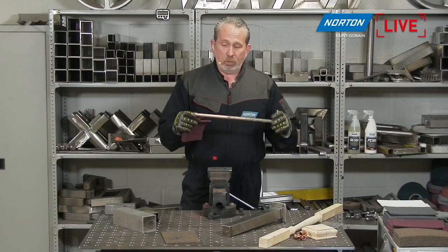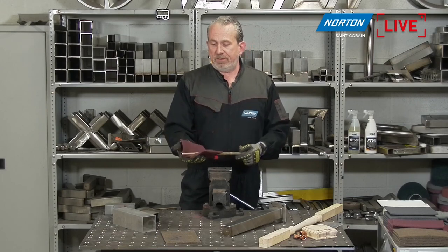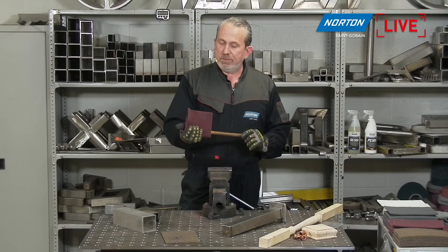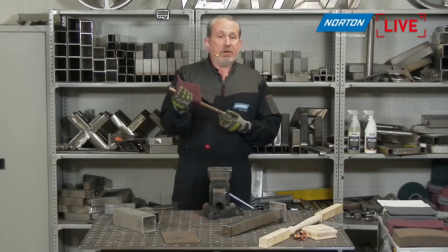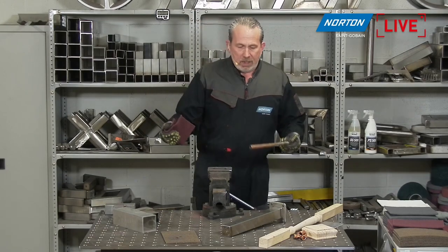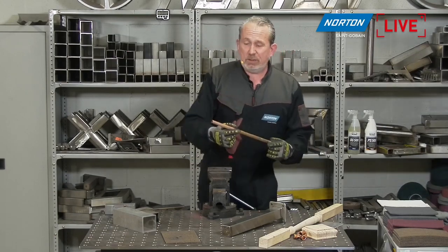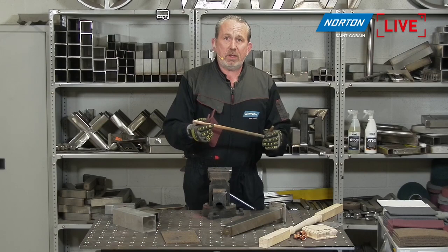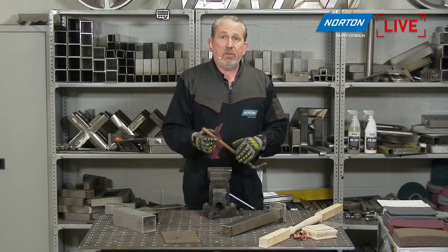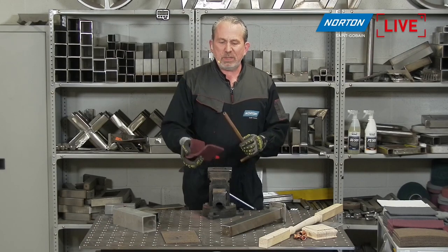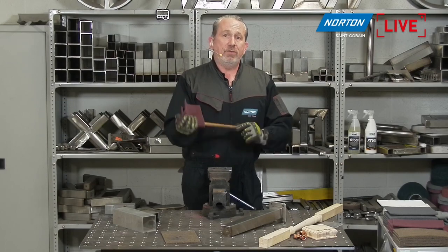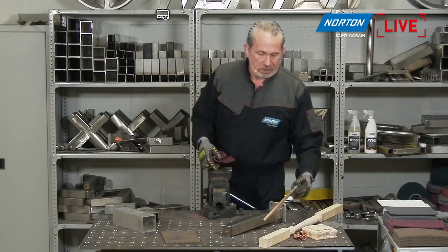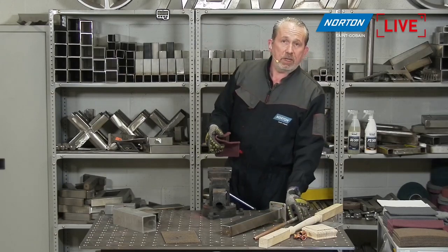And sometimes it doesn't look so nice, but you can see this finish you get from this hand pad is ultra bright and ultra smart. So you can finish anything like that very, very quickly. So easy, especially on materials like copper. It's soft, again, comparatively, and we don't want to damage that material by using an abrasive paper. It would dig into it too much, so we need a nice uniform finish on there to make it look good and ensure that it gets a good seal with the soldered joint on there as well.